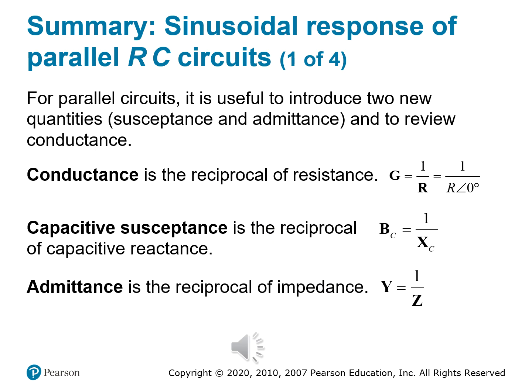So conductance, denoted by G. Remember, if resistance is how much a component resists current, conductance is the opposite, how easily it allows current to flow. It's just a reciprocal. G is equal to 1 over R, 1 divided by R, or you can also say 1 divided by R at an angle of 0. You're going to see this used often in parallel circuit analysis, and that's because parallel branches add conductance, just like resistors in parallel.